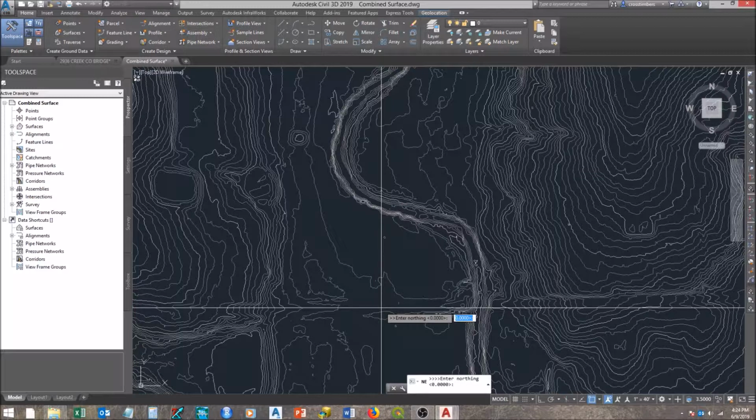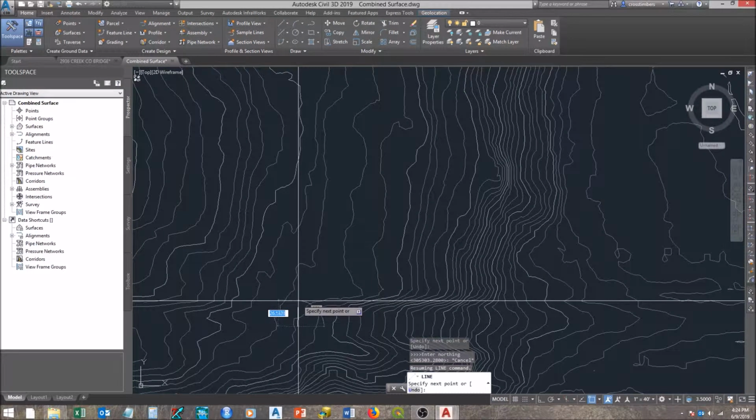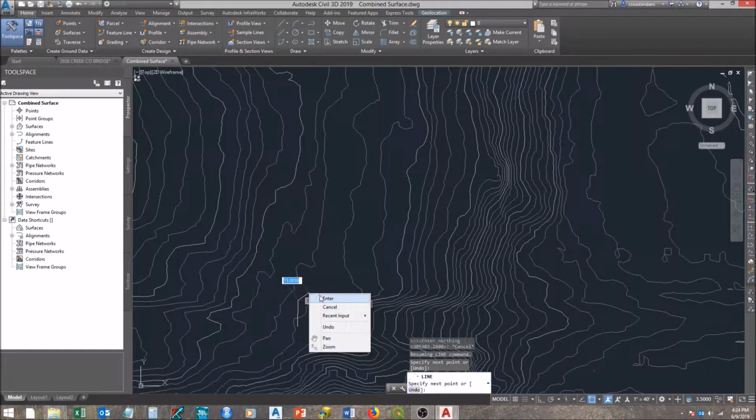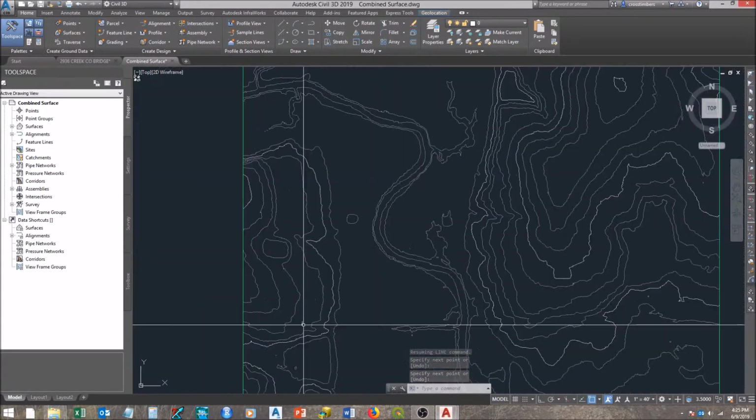So we'll type in our northing, which is 303.28, hit enter, and our easting is 2436000.73, hit enter. And it asks us to enter another northing and easting. We're just going to hit escape, and then you can see the line here, and we'll draw it out a little bit. And again, this is just so we can snap to this bottom point.